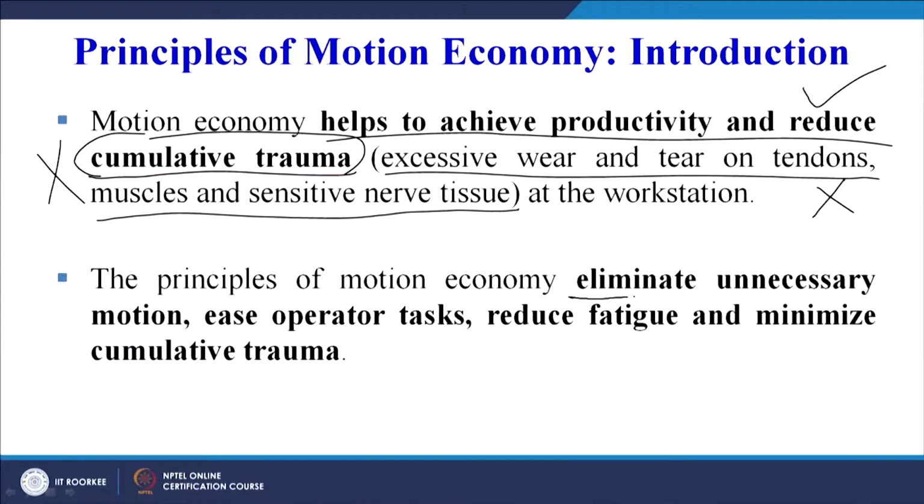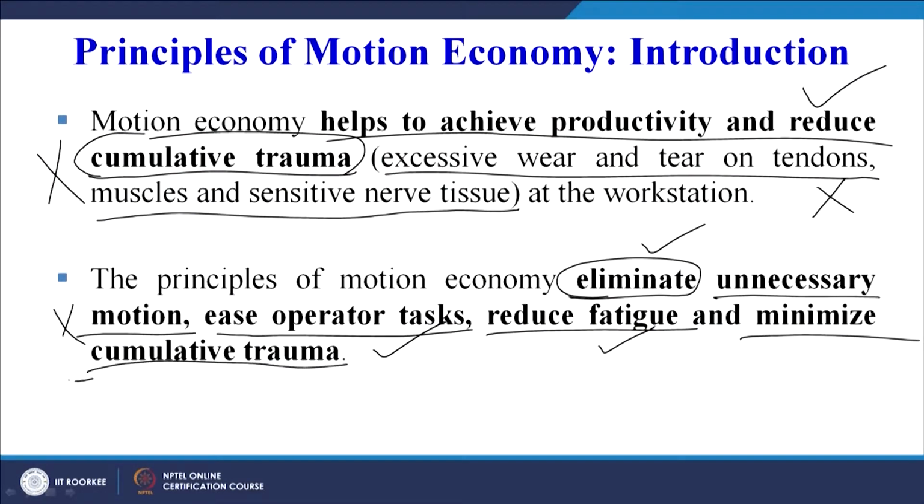The principles of motion economy eliminate unnecessary motion, ease the operator's tasks, reduce the fatigue and minimize the cumulative trauma, which we have already seen.